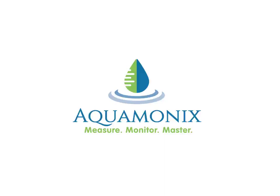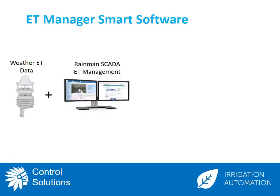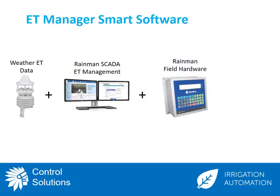I'd like to introduce you to the Rainman ET Manager. This software is designed to provide you with water savings through automatically adjusting irrigation programs based on ET values from a weather station. This software essentially pulls ET data from a weather station into the Rainman SCADA software. Calculations are performed based on hydro zone requirements, and new schedules are sent out to the Rainman field hardware, providing water when you need it and saving water when ET conditions are low. Let me show you how to set this up.